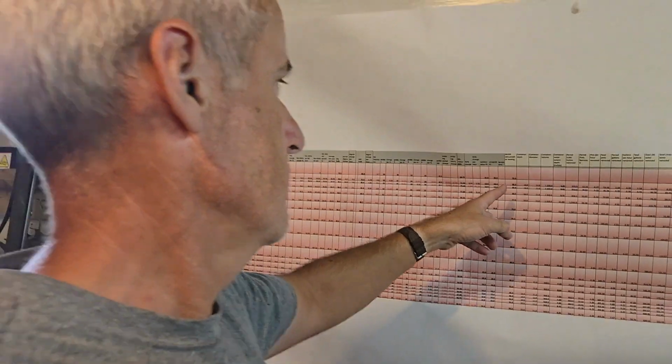We're actually thinking about buying another one, either the same size or we might go up a size with regards to its capability to draw more moisture out. Like this unit can draw, I think, 70 pints per day at maximum saturation. So if it's like 100% humidity in a space, it can draw 70 pints per day out. The best I've seen with this was, the guy was at 80% moisture and it was drawing about 50 pints a day.